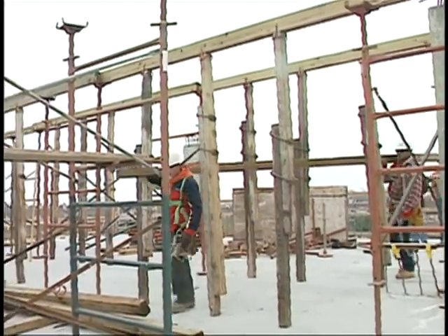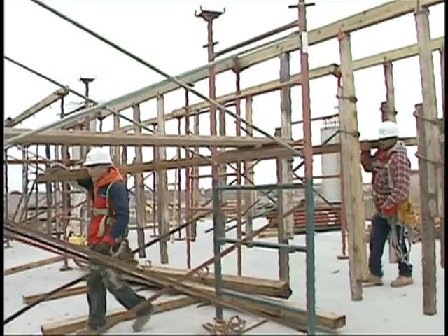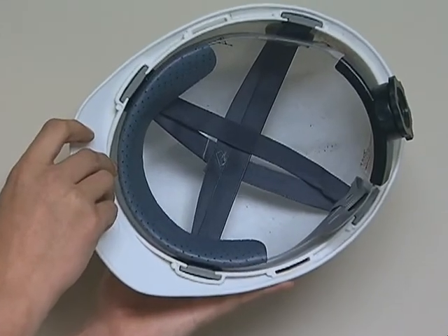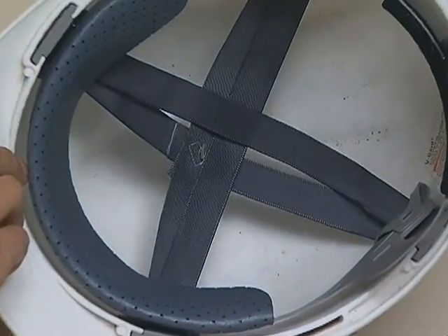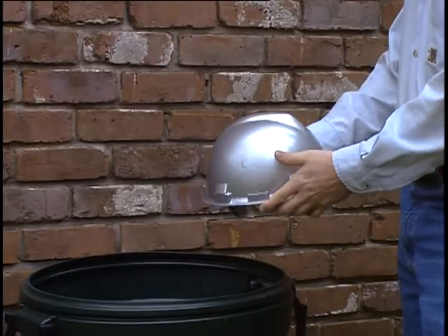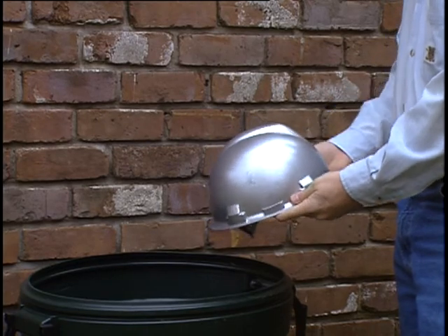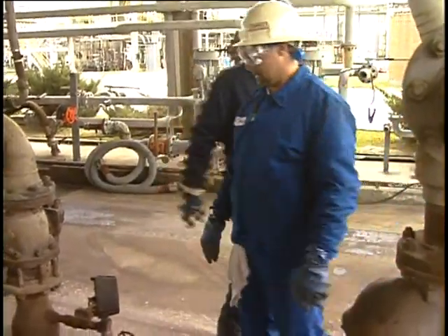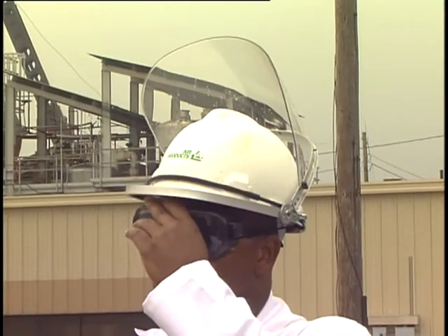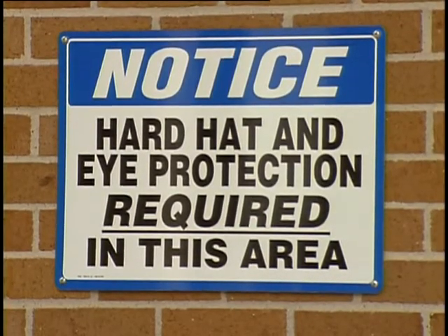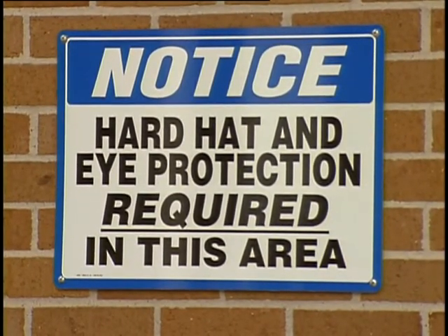Hard hats provide features that protect the head from impact by providing a hard shell that resists and deflects objects from hitting the head. The suspension system inside the hat acts as a shock absorber against falling objects. Some hard hats insulate against electrical shock. A metal hard hat is outlawed at most construction sites and facilities since it offers no electrical protection. Hard hats shield your scalp, face, neck, and shoulders against falling fluids. Some can be modified by attaching face shields, goggles, hoods, or hearing protection. It is the employer's responsibility to ensure hard hats provide sufficient protection.